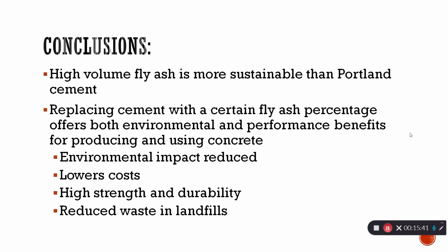The fly ash usage has to be optimized to ensure that the fly ash is being used to its full potential and benefits it can provide to the mixture. It reduces the environmental impact of concrete production, lowers costs, concrete's properties can be improved with the use of fly ash, and landfill waste is reduced, thus making fly ash a great replacement for cement if one wants to have a sustainable concrete with high strength and